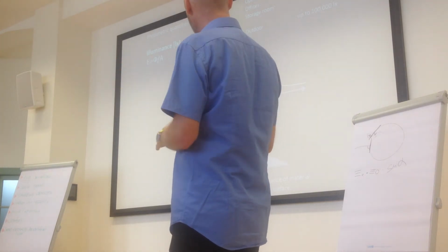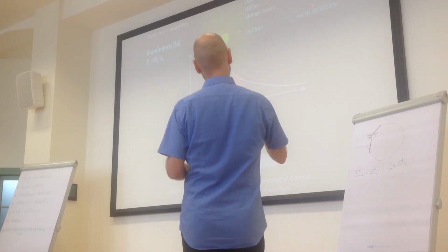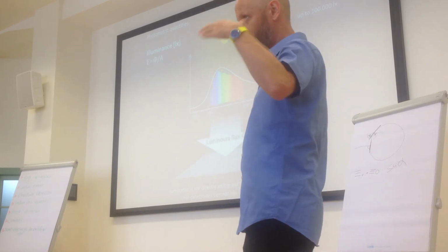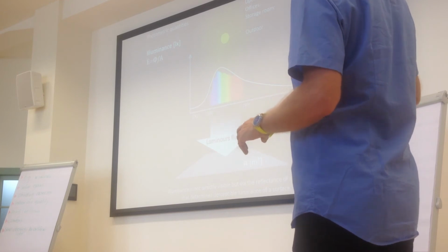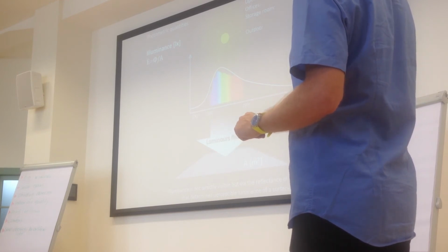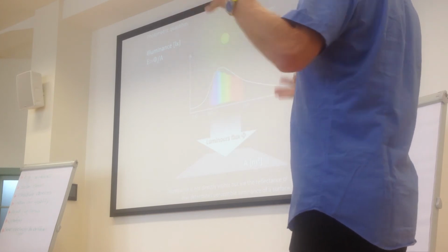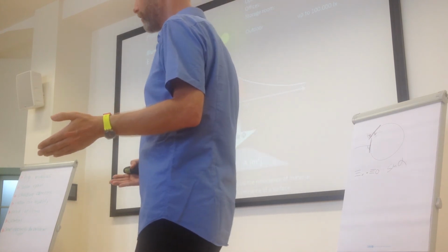In storage rooms or with lower visual requirements, we should have about 100 lux. On a bright summer's day, like this midday, we can assume a lux level outside of 100,000 lux. So you see that the gap between inside and outside is very, very high.